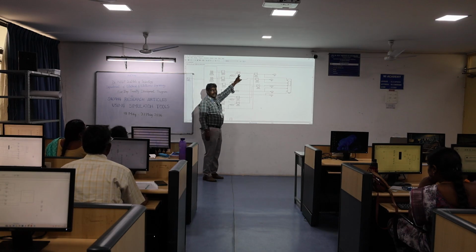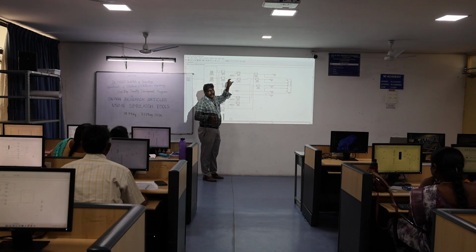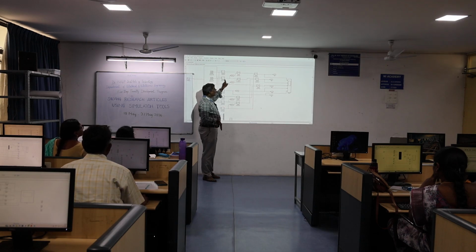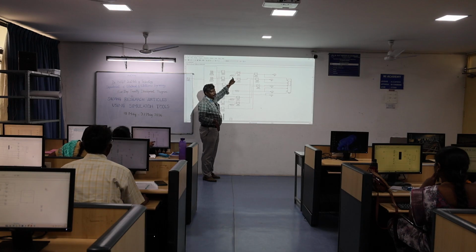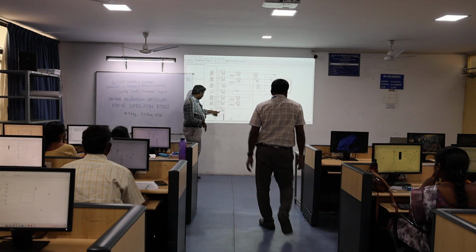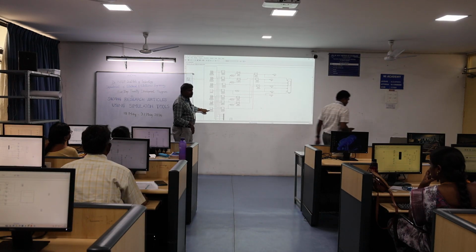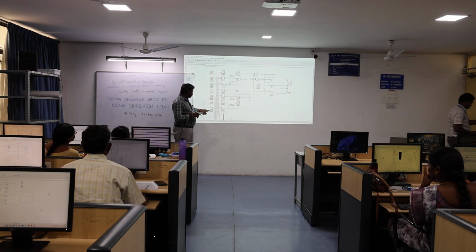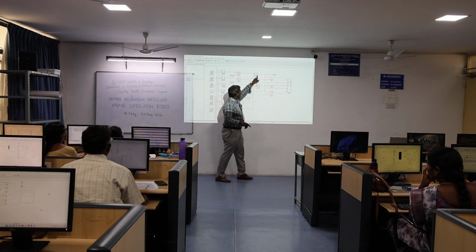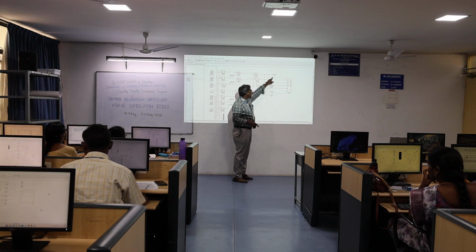Next you can take the logical operator from the Commonly Used Blocks and use it as an AND gate. The output of this relational operator is connected to the first input of the AND gate. The output of the second relational operator is connected to the other input through the NOT gate. Then it goes to the OR gate. Then for the last triangle, -0.6 to -0.9, the output is connected to the OR gate.